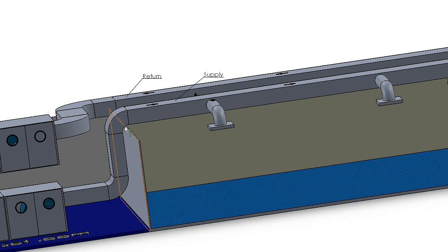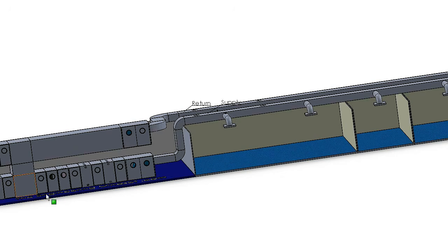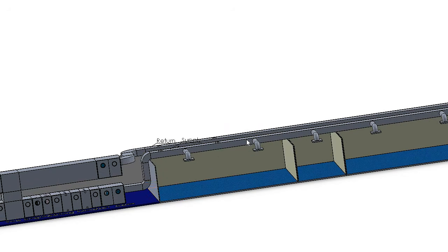It could also go into a riser here, and that can go up, and that could spread to several floors. It could go down below as well. These could potentially be positioned on the roof, and these could be supplying all the floors below. This could be in the basement. It could be feeding all the floors above up to a certain height, or it could be, in this example, where you've got one AHU per floor. Maybe these are all tenanted offices, so a different company rents out each floor and they want full control of all their air conditioning, HVAC.